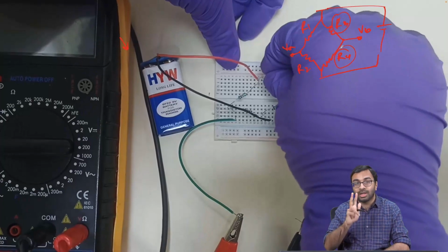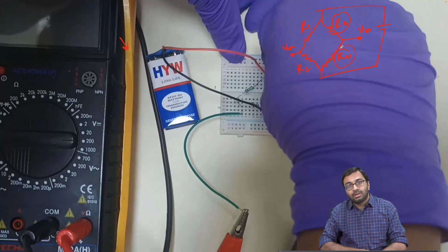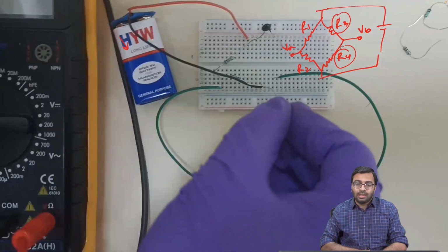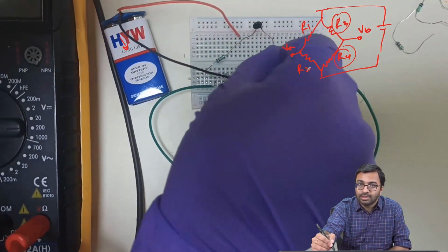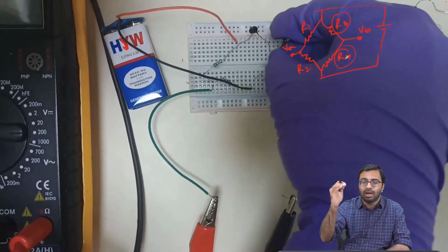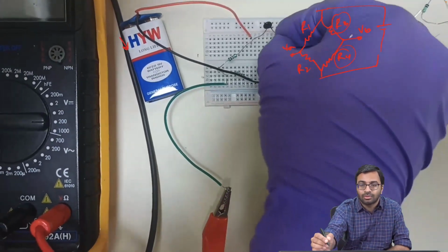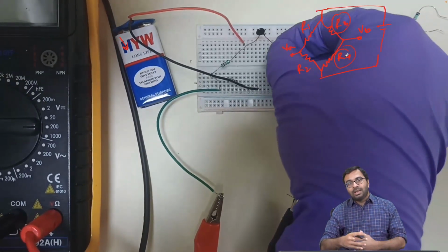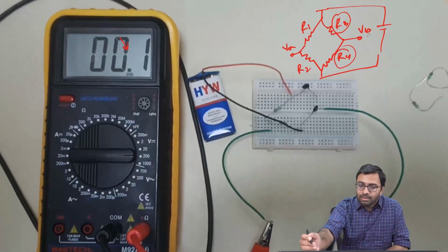So we have taken two thermistors and we are replacing R3 and R4 with similar thermistors, and both the thermistors have the same resistance value. So in this case R1 and R2 are the same resistance, R3 and R4 are the same resistance. So your R1 by R2 is equal to R3 by R4. So it's basically 1. If R1 is equal to R2, then this is 1:1. R3 by R4 is also 1:1. That is how we are creating a balanced Wheatstone bridge, so that we have an output VAB which is equal to 0.